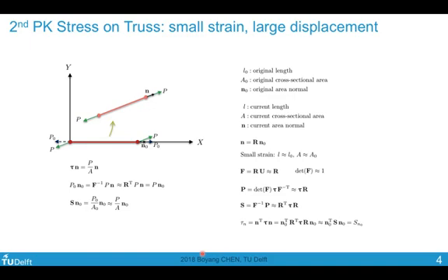They are the same. So this means that if I calculate my second Piola-Kirchhoff stress from my constitutive law through the Green-Lagrange strain tensor, and I obtain the stress components along the normal or transverse directions in the initial configuration, then under the assumption of small strain I can pretty much say that the normal and transverse stresses in the deformed configuration, the true stresses, are of a similar amplitude as the ones in the initial configuration. They are just rotated in terms of direction, but the magnitudes remain roughly the same. Of course, once we remove the small strain assumption, the magnitude will also change, scaling with your change of area and length. But in most aerospace applications, we are concerned with small strain, large displacement analysis, and this should apply.